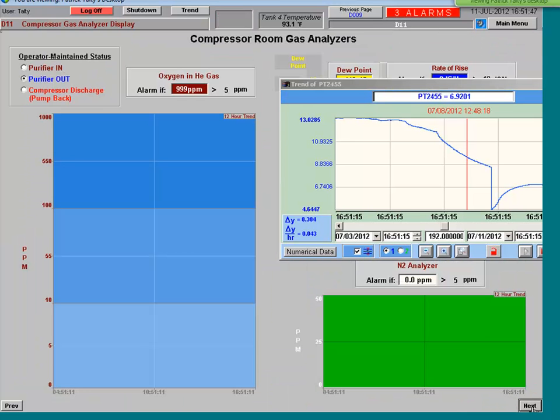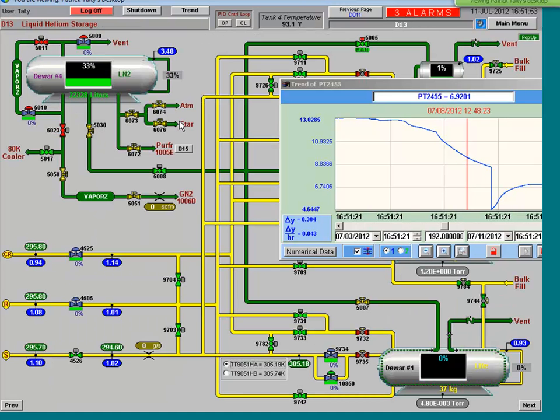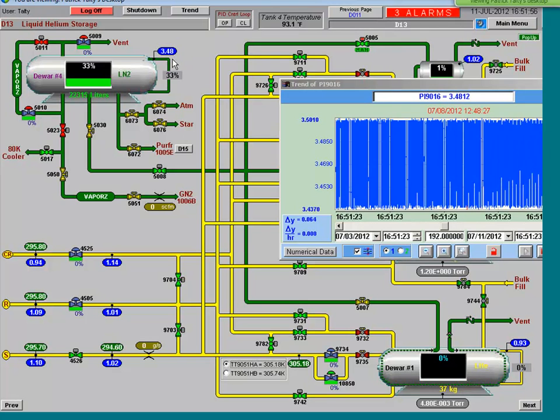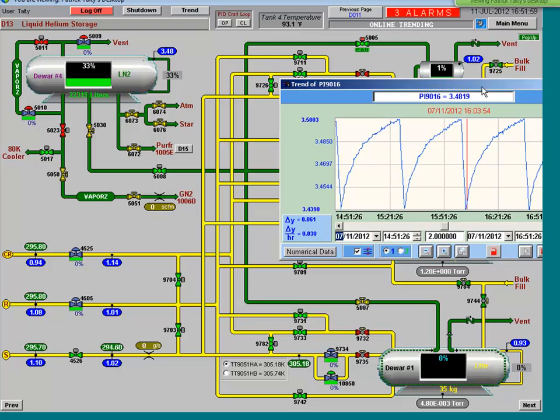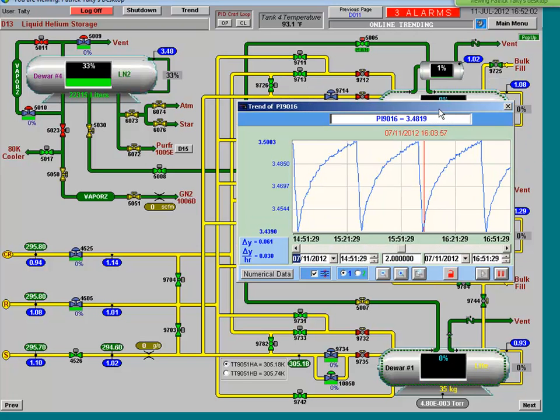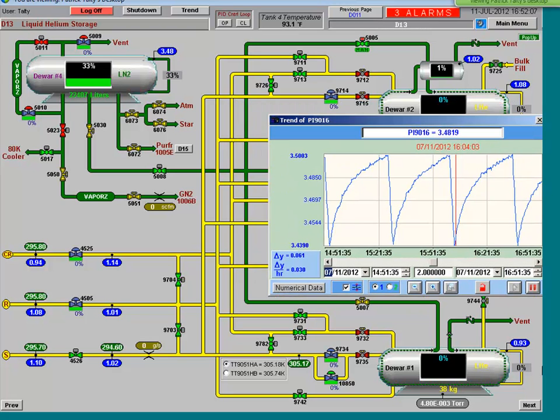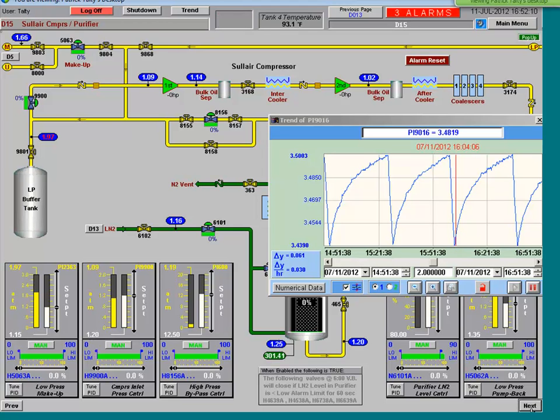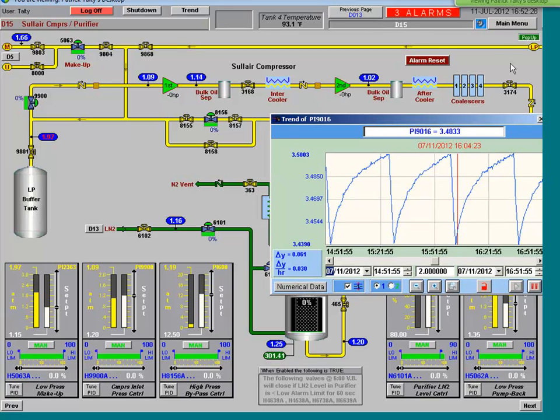This is something that our old DCS interface didn't have. All of the trends had to be hard-coded, including the limits. So to have the ability to basically trend everything, and that's 3,000 process variables that we trend, if I didn't mention that, is invaluable, because you really get a great idea of not only what's going on, but maybe what happened a week ago, or a month ago, or 2 years ago. We have several years worth of data that's online, because hard drives are so cheap. The 300 gig Velociraptor, I think, is like $200 or less.